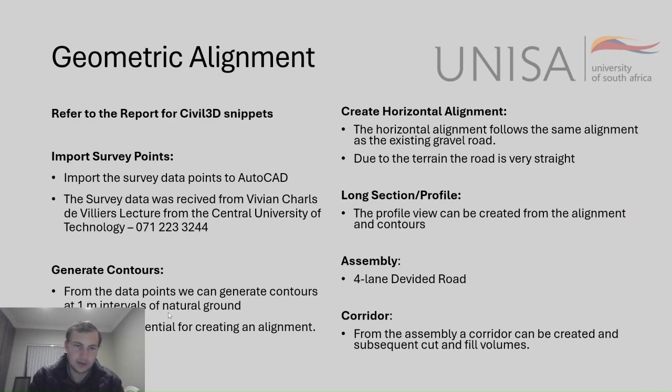1 meter intervals of the natural ground level there. Yes, I kept it on 1 meter. I think that's quite standard. This will be essential for creating the alignment, which is the next step.